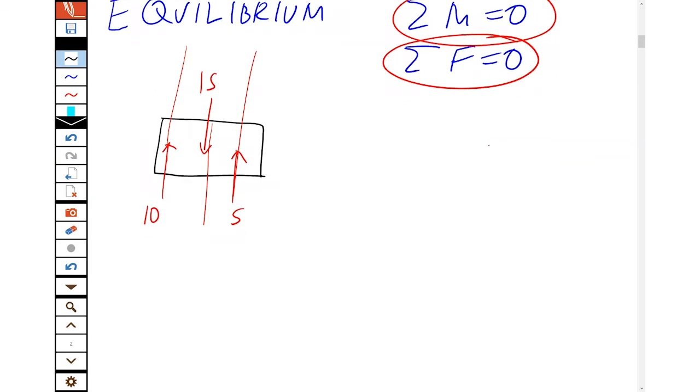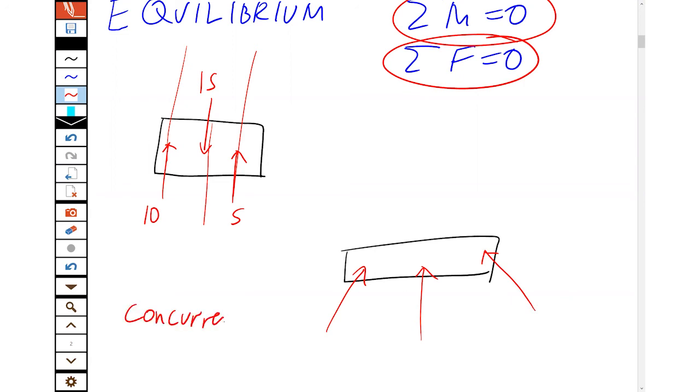For any other situation, if you have just 3 forces acting on it, and it's in equilibrium, the 3 forces must be concurrent, which in this case exactly means they must all cross at one single point. Because that means, well, you can see if I took the moments around that point, the total moment would be 0, because all the forces are pushing on the pivot. In the same way, a force pushing on a door hinge won't give us a moment, it won't make the door turn. Now that's not usually true.